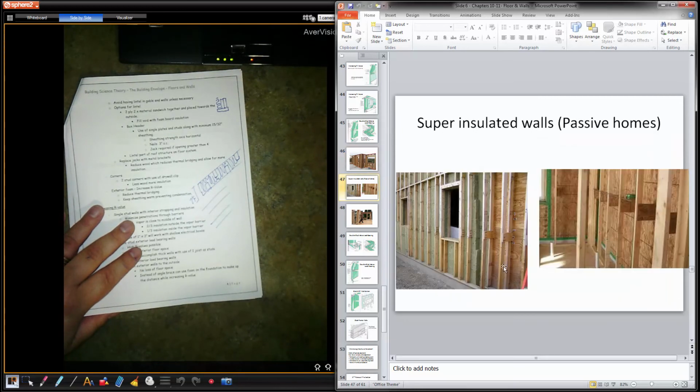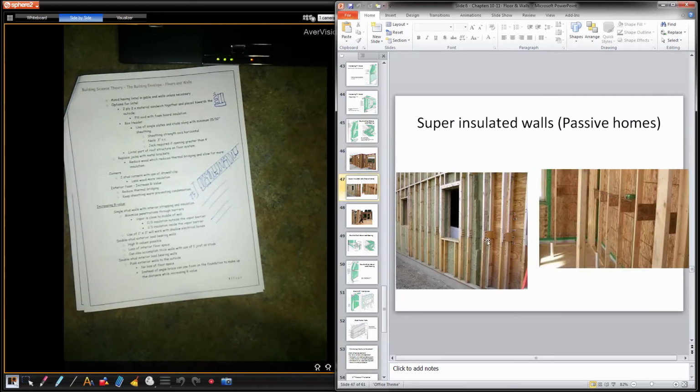Okay. You see this a lot in passive homes where they actually build their own studs. So they have a 2x4, 2x4, and then they have plywood sandwiched in between. Okay. So they're able to get rock solid in between those gaps, as well as in between these trusses, if you will. Same thing with plywood, and then again a bigger gap in between. So you can see they have sheathing on the exterior already put in place, and it's all taped. So that's air barrier on the exterior.